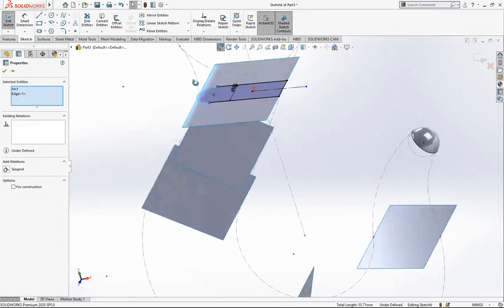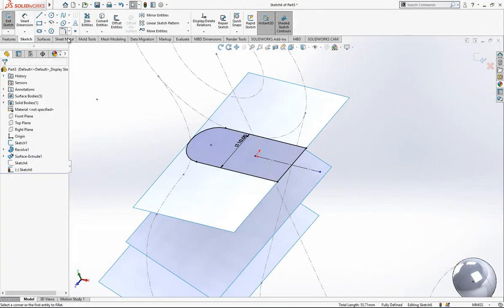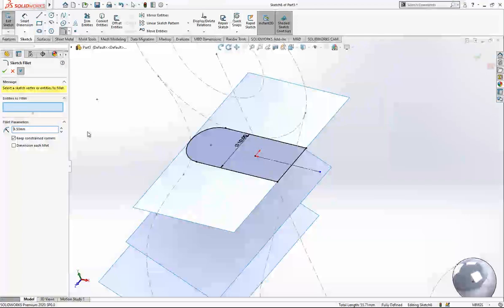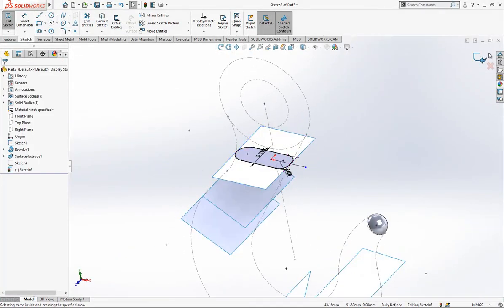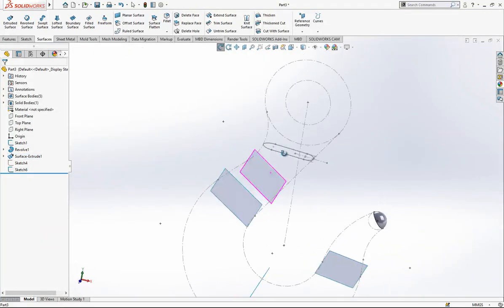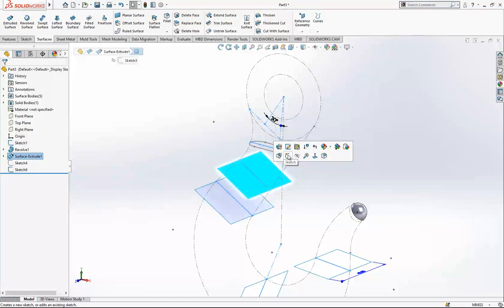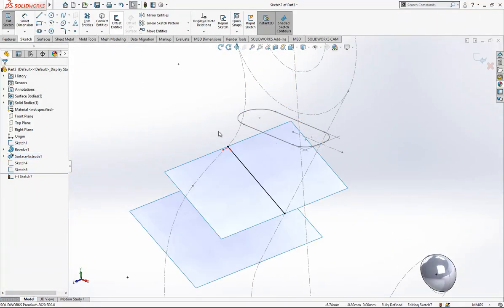And because this line was defining our section width, you say here a tangent, and then 4.5 millimeter radius, or was it 4 first? Sorry, there are a lot of steps, sometimes I'm forgetting. This is the first section, then we can hide our profile, and the second section will be here, and I can convert this line,